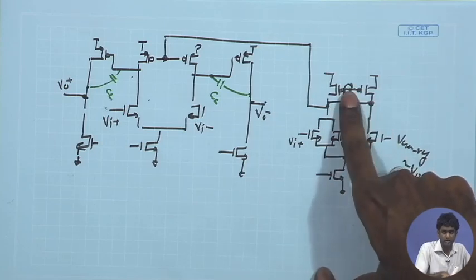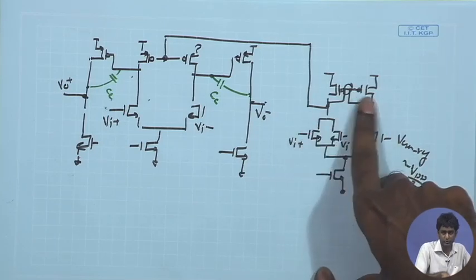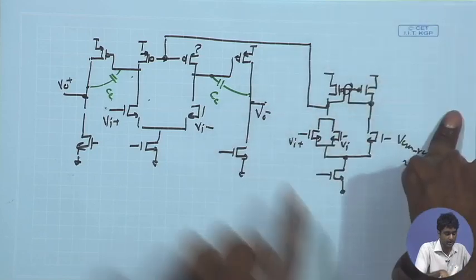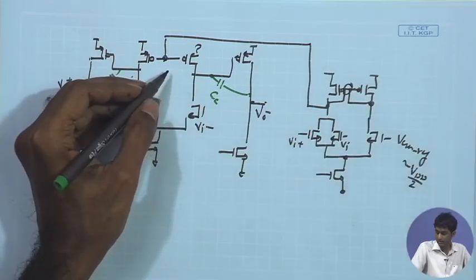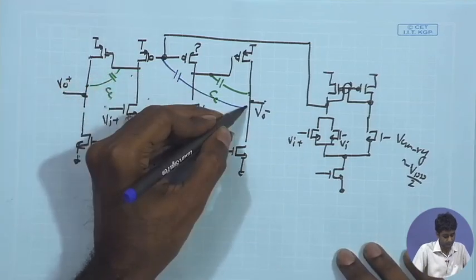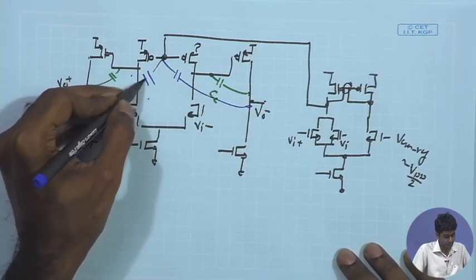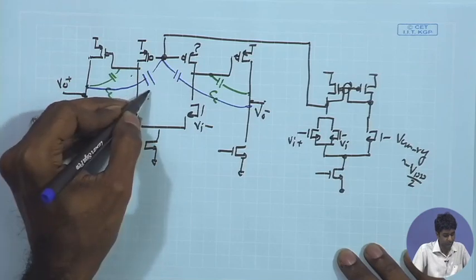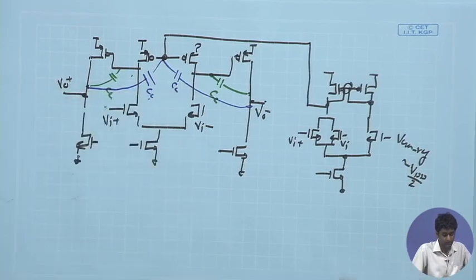So, if I stick to a current mirror load, that means this stage is going to have a large gain of GMRO, and then we put a cap between these 2 points for the compensation of the common mode loop. This is what are going to be the pros and cons: whether it is a good scheme, whether it is going to give us appropriate compensation for the overall loop response for the common mode.